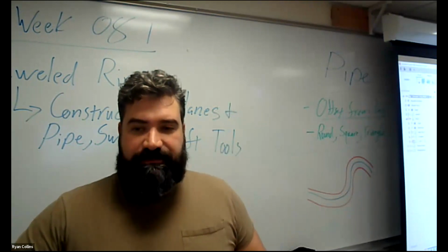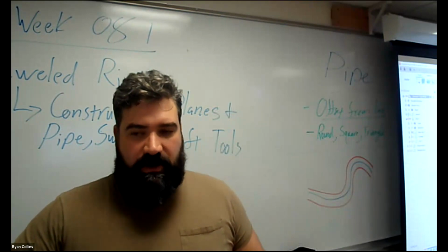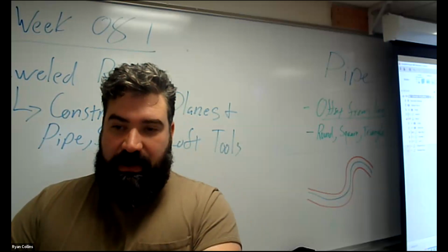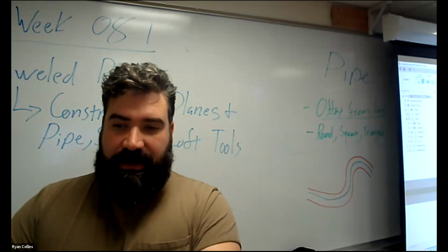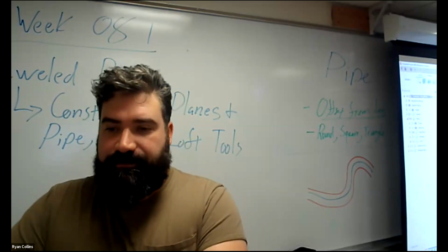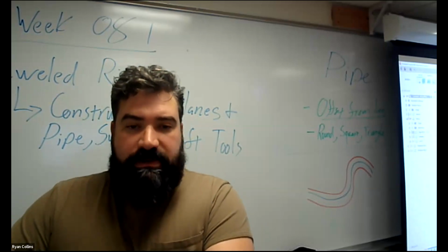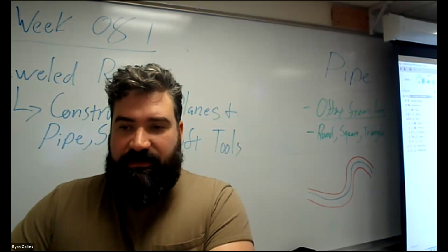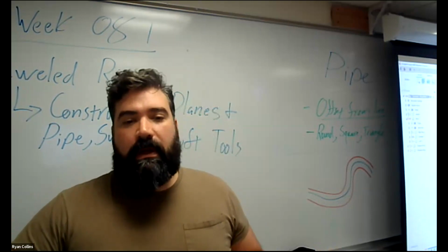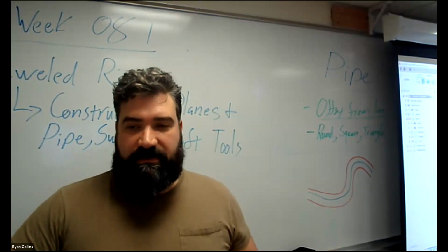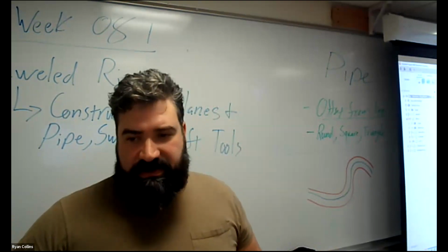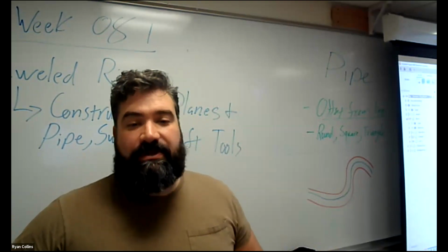So just for reference, like I said, pipe ring, don't make just one pipe. But what we could do is play with offsetting them and making variations and then linking them all together. So you can make like this kind of like knotted ring design. That's a cool one. Sweep. Yeah, you just have the one profile, so that's kind of like a really basic ring. There you go. Loft allows you to make something a little bit more involved, but still like a smooth transition, that sort of thing. And you can always add to this.